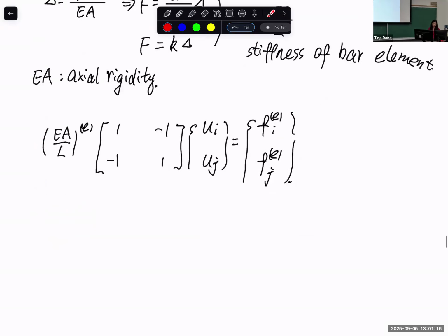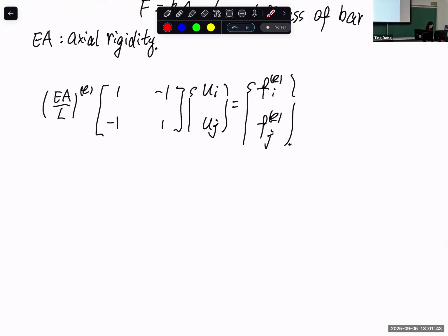So if we have a system with different parts, even with the same cross-section shape, but made from two different materials, the Young's modulus is different, which means K is different. So even if you see it as one bar, you need to discretize it based on the material. A simple example: